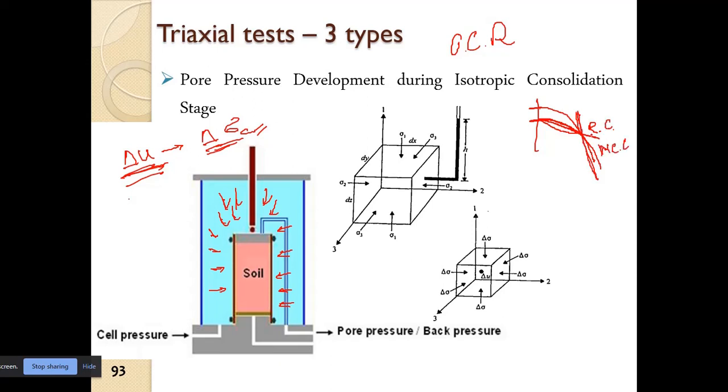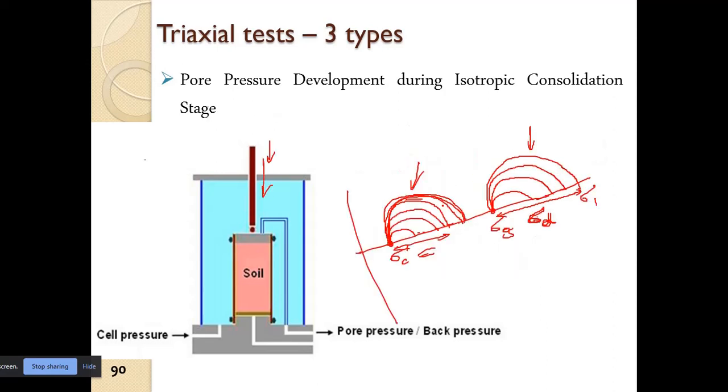So we will know that this is the over consolidation stress. It has been loaded to this stress previously, so from now on it is again getting consolidated. There is again rearrangement of the soil particles, and drainage of pore water out of the soil. So these are some important considerations.